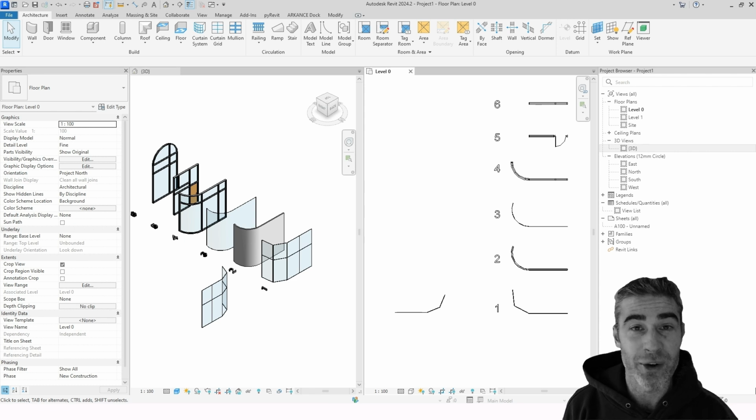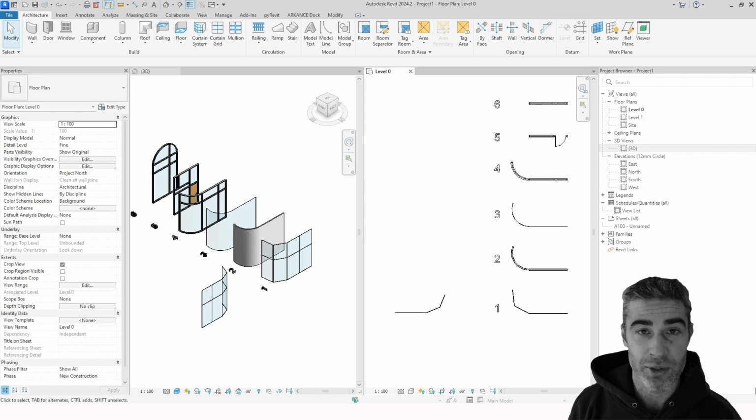So instead of a curtain wall, you can actually fake that curtain wall panel to be a wall, and it will start to actually move like a wall. Now, the issue I find is that your mullions still aren't moving with that, and so it becomes an issue. So what I have found is that we can add certain profiles, add certain sweeps to walls that allow us to create this curtain wall lookalike.